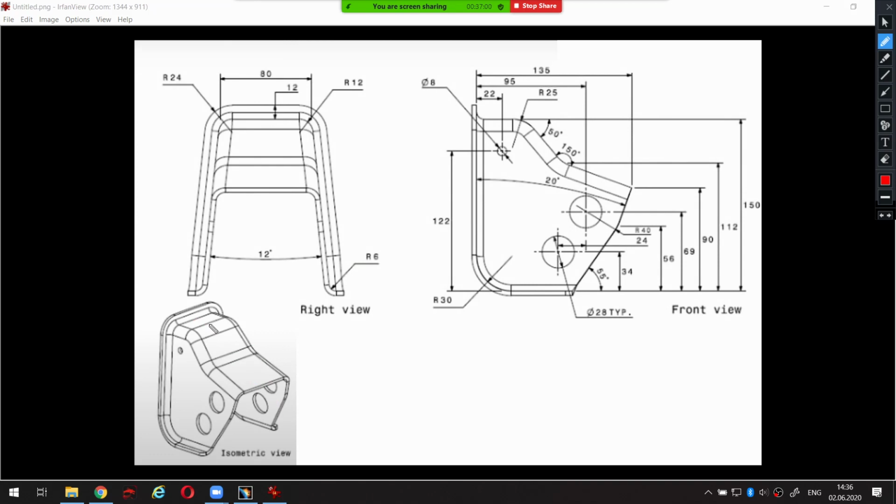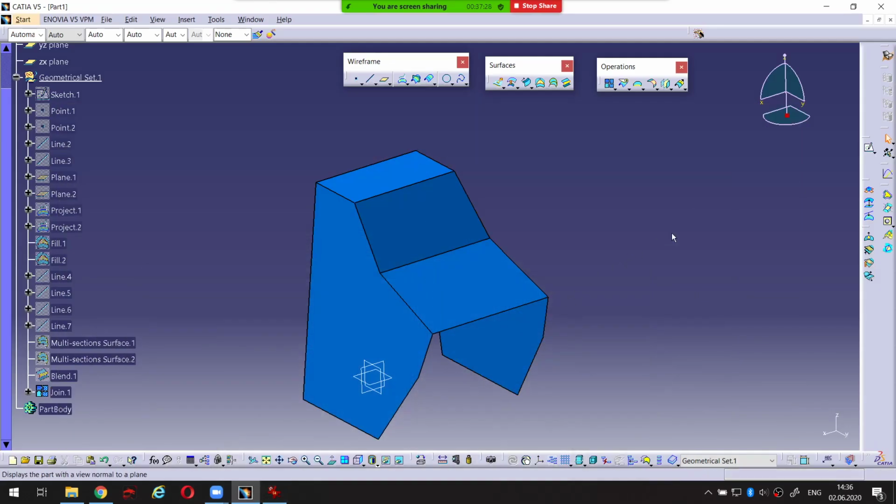So now I want to create these fillets, 1, 2. These fillets are shown here. I mean the radius, the dimensions of these two fillets. Here the first radius is 25, and here, as you can see, the radius is not shown. Let's assume the radius of this is also 25. It should be so. And let's create this.